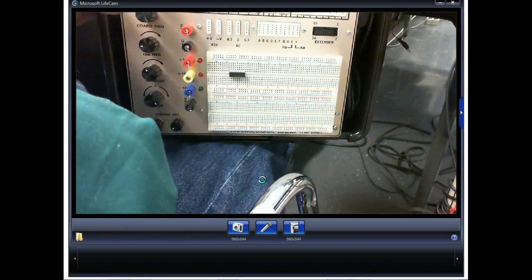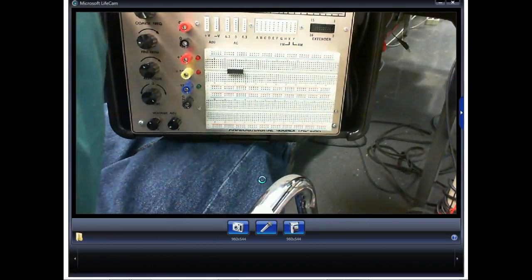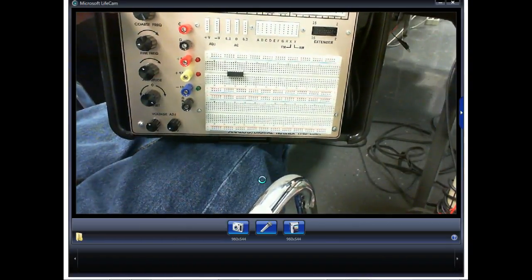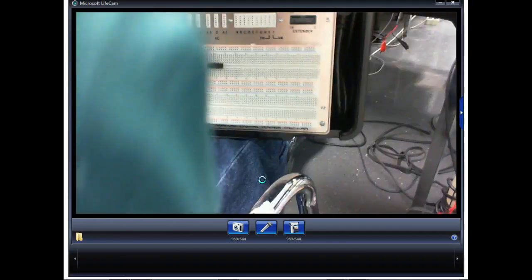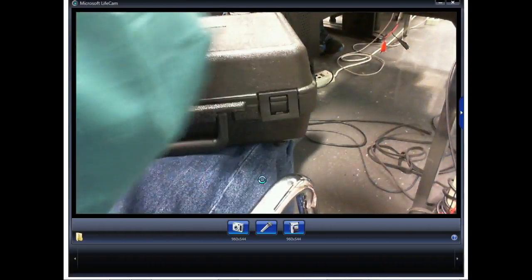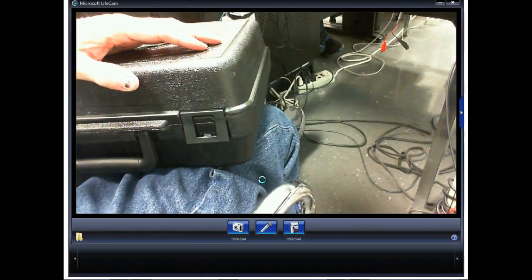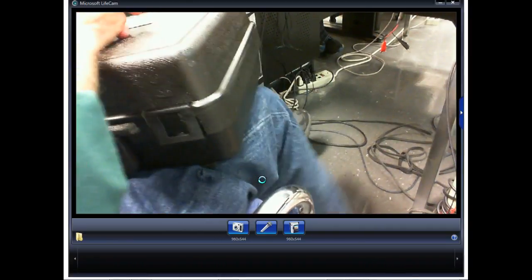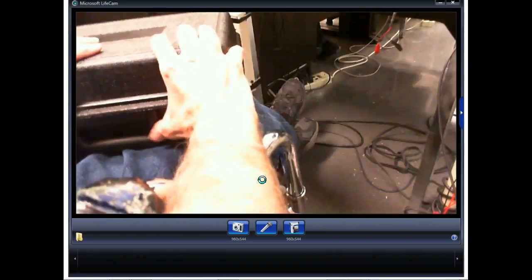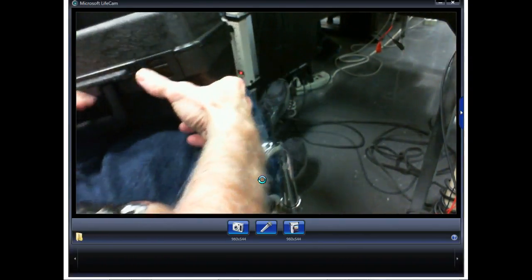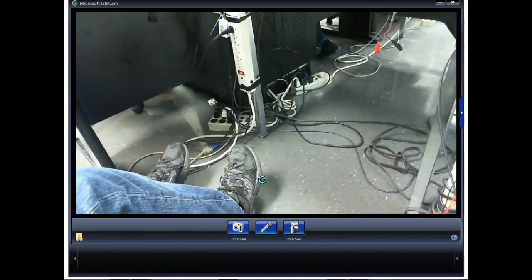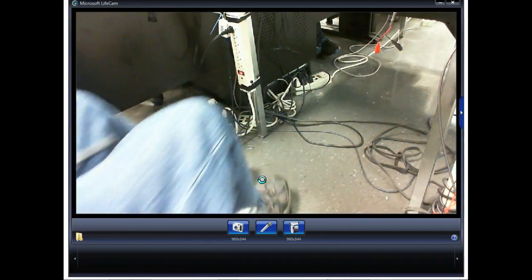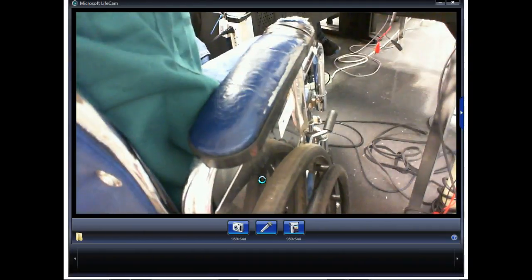I'll make sure you're using pin 7 and pin 14 for this chip. Now, don't take for granted that the upper pin on the right is power and the lower pin on the left is ground, because as soon as you think that, you'll hit a chip where they're not. So that's why we need to look at what we call the pin out. Y'all understand what the pin out is? It shows us what each pin is assigned to.